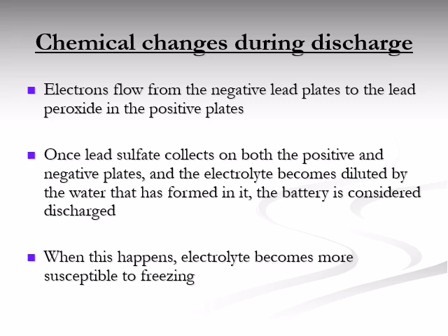During discharge, electrons move from negative plates to positive. Lead sulfate builds up, and the electrolyte becomes diluted, making it prone to freezing.